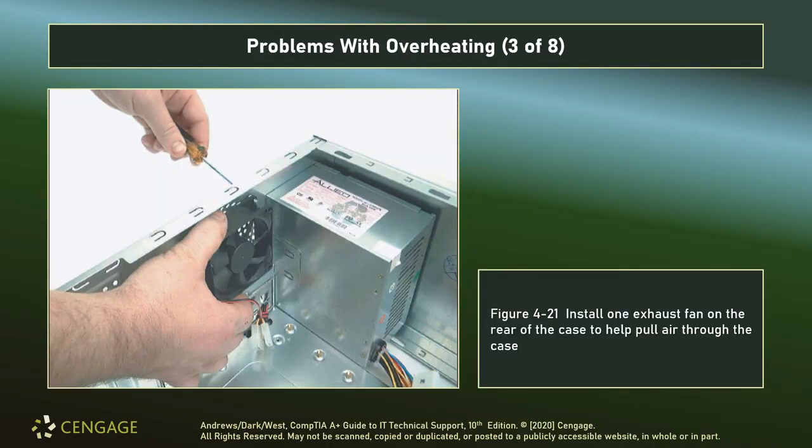Here we can see that their power supply has what we'll call a front-facing fan. It faces towards the front of the case rather than there being one underneath. I prefer the ones that have both, but if you have to make a choice, I like the ones that are on the front. It tends to be a little bit better at keeping airflow moving in the direction that we would want.